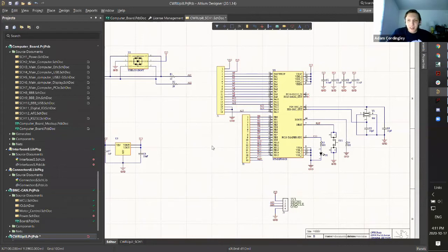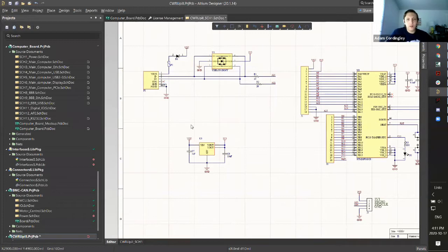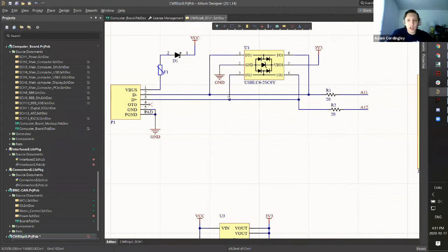So reference designators. Now we've annotated our schematics, and we have our nets all named. Everything's connected up. There's one other thing I want to do, which is a little bit of an extra thing. These USB lines, ideally, should be differential pairs. So I need to tell the schematic that these are differential pairs. There's two things you need to do. One, you're going to place a parameter set. Right-click here and hit differential pair. Place that parameter set on both of your differential pair lines.